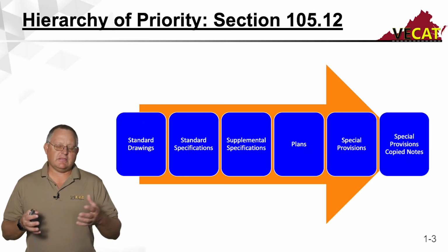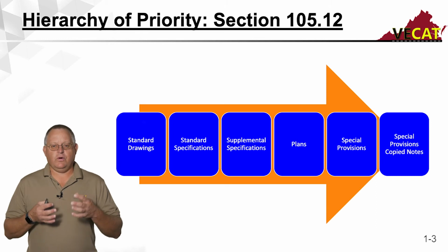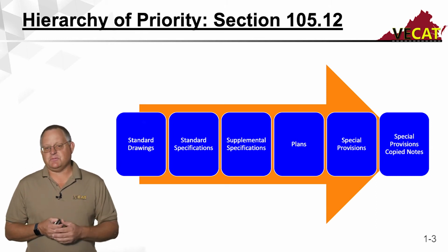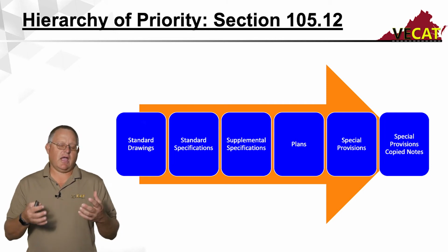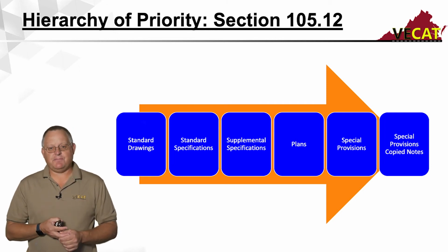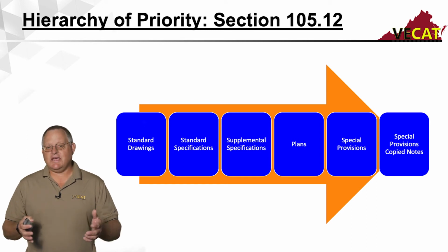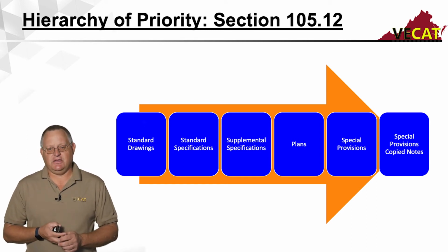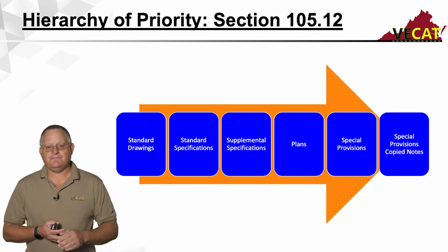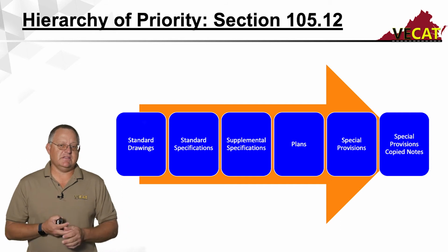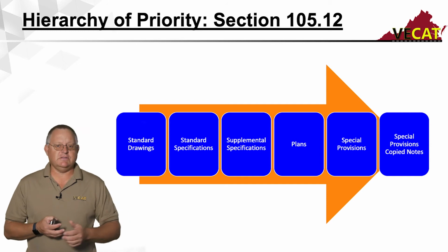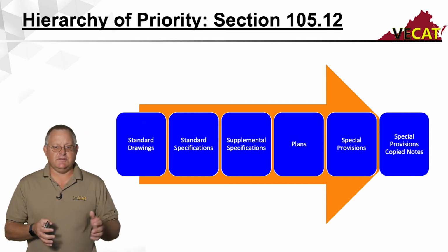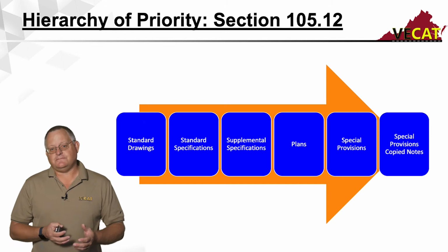So when we look at the project itself, what is the most important is that special provision copy note. So when your company gets a project, a good question to ask is, are there any special provision copy notes specific to this project? Could be sampling, but it could be there's some differences in the testing results. So if you're a plant level 2 technician, maybe the voids in total mix changes for a specific material. You need to know what those are.